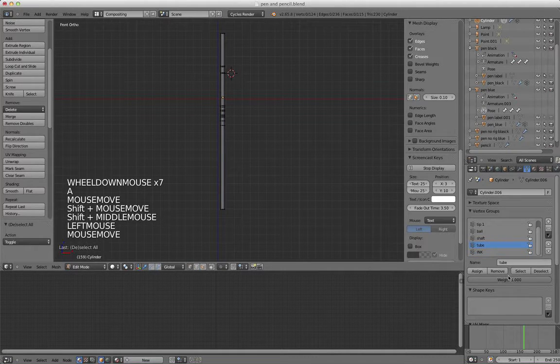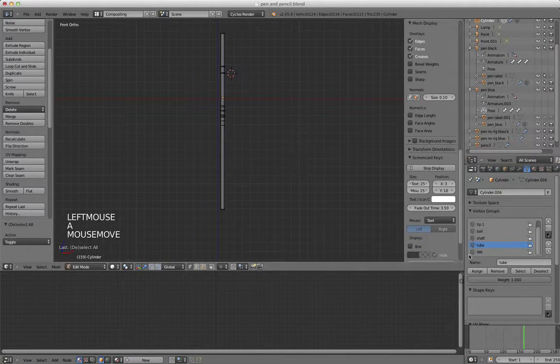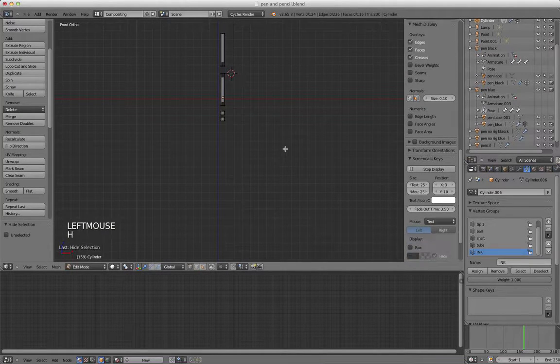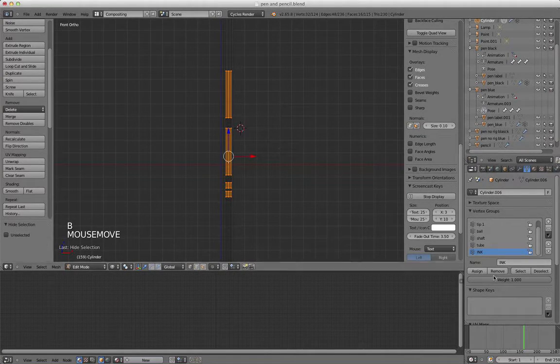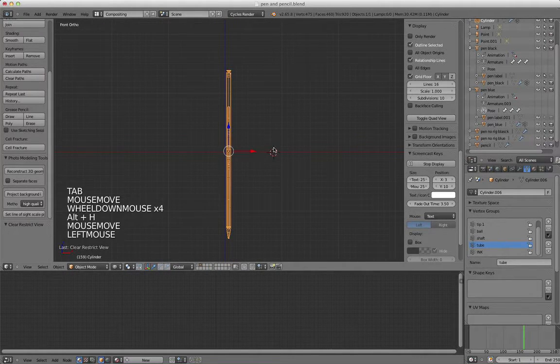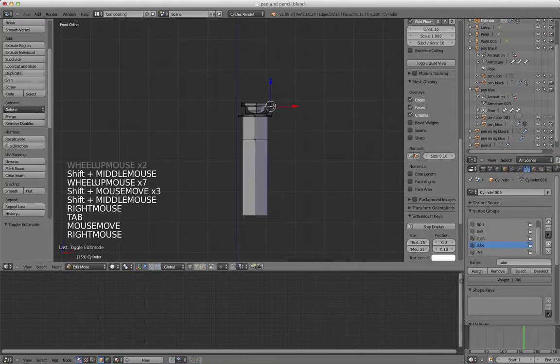So if I do tube, it kind of selects all of them. Okay, so I'm going to remove those from tube. I'm going to hit ink, select the part with the ink, and then press H to hide those, Z to make it X-ray, B to do a box. I'm going to select this part, and this is the tube part without the ink. Okay, so assign that to the tube. Now Option H. Let's go up and put this plug back in, and we should be done.